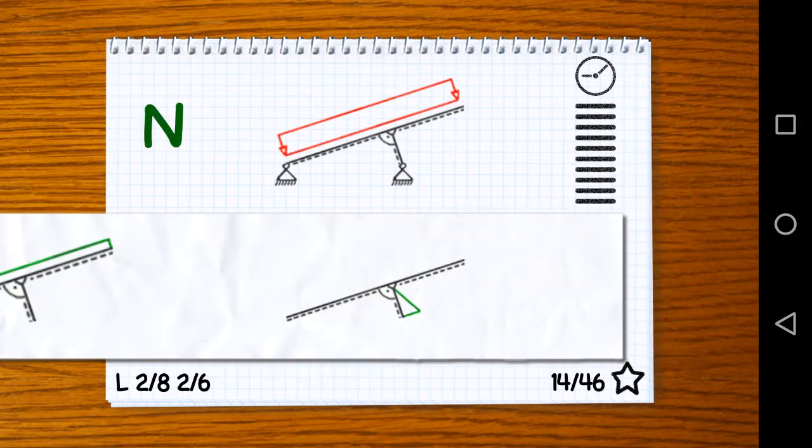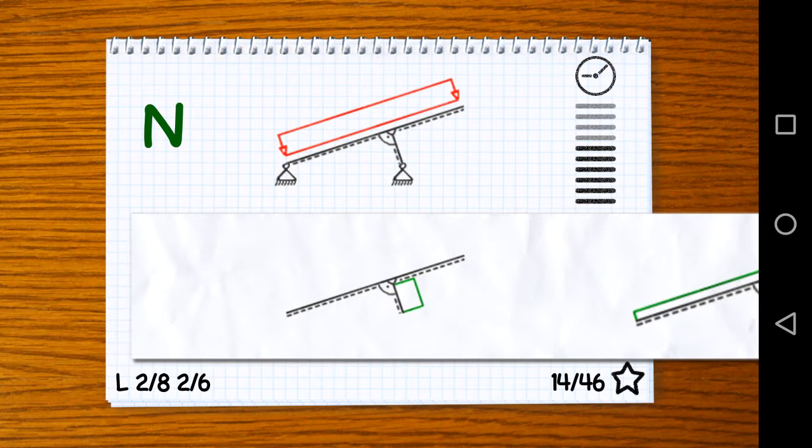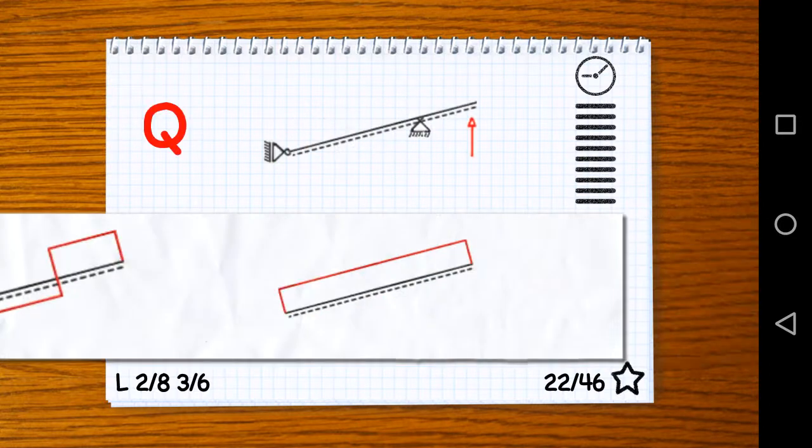Let's move forward. A distributed load on the inclined beam up there, yeah? But that distributed load is perpendicular to that beam, so it's not going to create any normal forces in that inclined beam at all, okay? But you can see that the strut down there, that bar that's supporting the inclined beam, is going to be compressed, and the whole distributed load is basically pressing that single column, okay? So negative force is compression, negative here, down there.